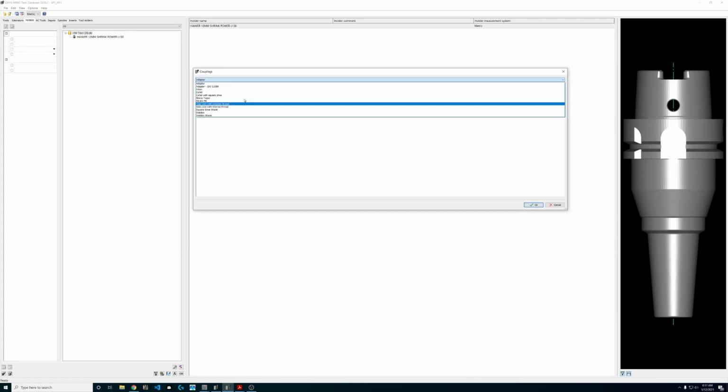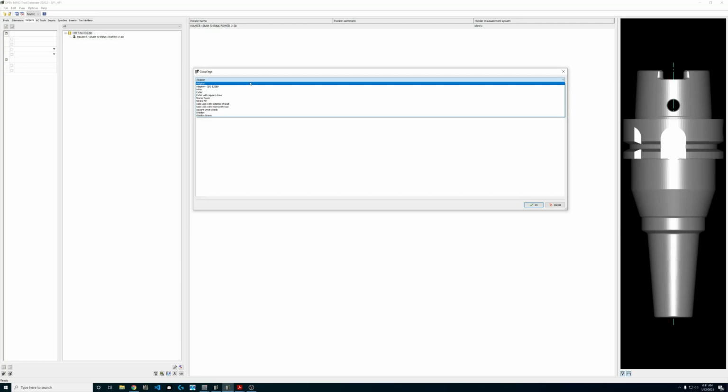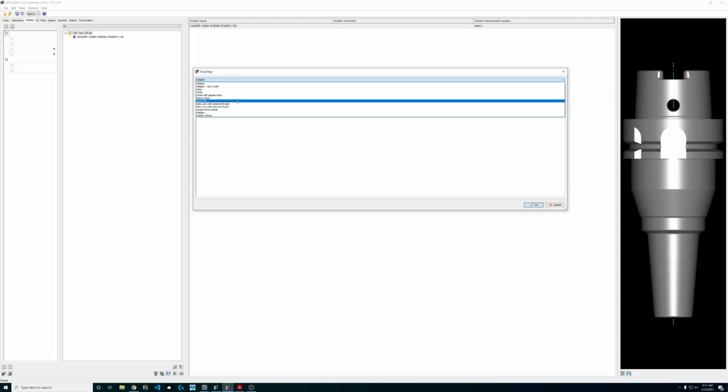There is a lot to take in here, but basically what you need to know is things that match can go together. We like to use Morse Taper as our catch-all because it's sort of a nothing. It doesn't have any value or data on the hyperMILL side attached to it. So we can freely define an ER32. No, that's not even a great example because technically we have collets that work fine. Milling chucks with straight collets. Or maybe you have some, we're just trying out now the MST two-piece shrink fit holder. It's got its own unique coupling geometry. So I'll use Morse Taper to define both the bottom side of the master holder and the top side of the extension, and those two will always mate together.